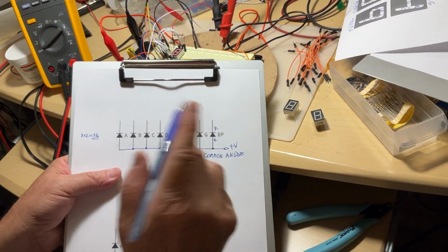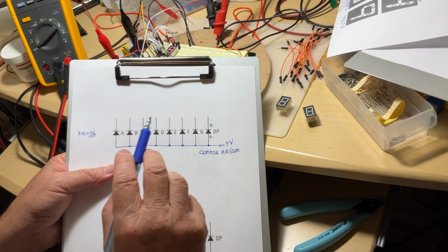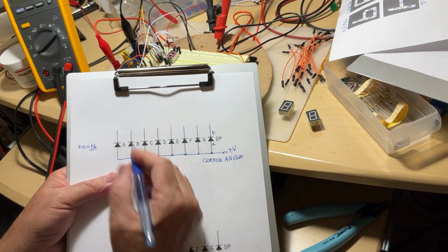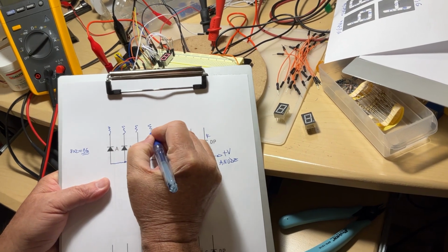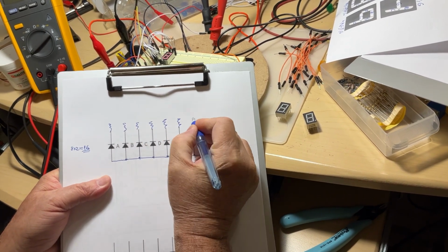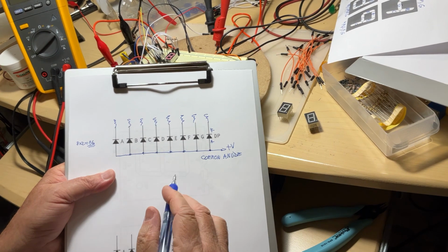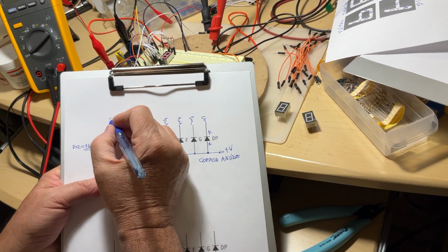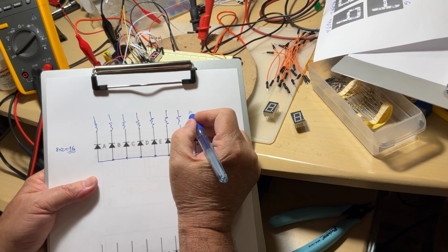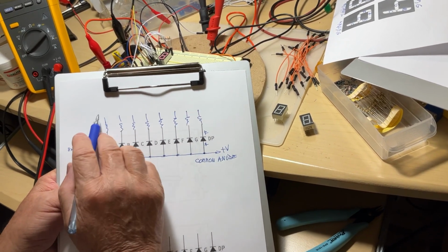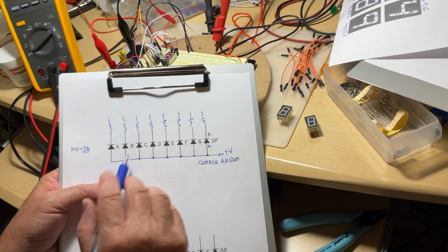Now remember, you won't leave any LED energized without a resistor. So here you are going to connect some resistors. And to close the loop to the power supply, from each resistor, you have to provide a kind of negative voltage depending on what segment you want to light up.